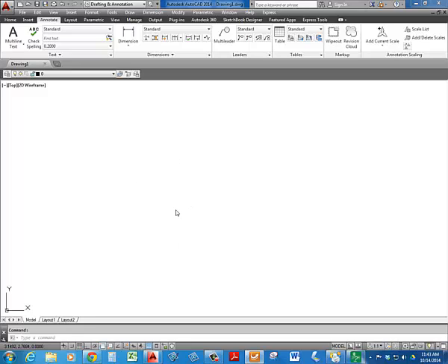Once you are at this point, and my screen is white, and you can change colors of the background, you can just start typing. I like to click down here where the command line is. Your command line is probably floating. I've got mine docked. We'll cover that a little bit later. But if you just start typing at your keyboard, type the command startup, which is all together one word. It can be lower or uppercase, doesn't matter. Startup and press enter.